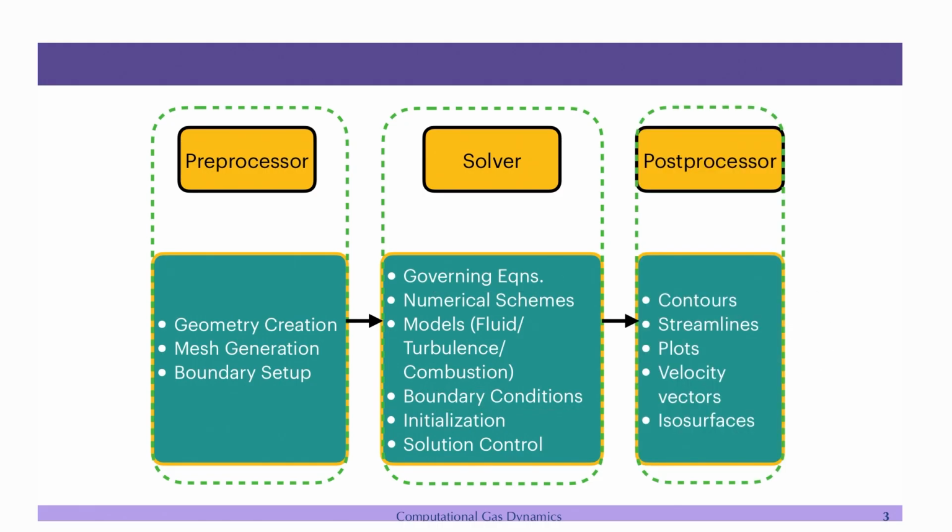So finally, once you have simulated and let us say you have got a solution, so let us say you are doing a RANS solution, then you will have some convergence. You start from some big value, and then it will go to, let us say, 10 power -5 or -6, and then you say my solution has converged. So, this may be my momentum, this is my mass, this is my energy, and so on and so forth. So, at this point, when it has reached this stage, you stop the solution, and then the next thing is to analyze the solution. So, how to analyze? There are several ways. First of all, how does my flow look like?